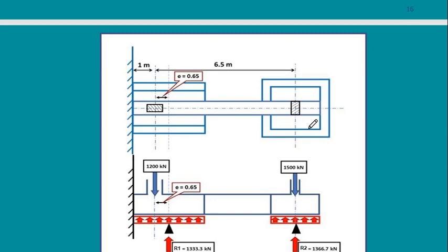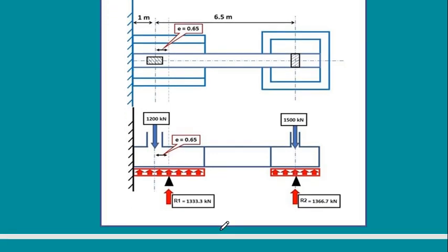What are the forces? Just for the designing of the footings, I was using the working loads because I'm just designing areas and so on. Now I'm going to design this strap beam. It's a beam. So I'm going to design the depth of the beam. I'm going to design the amount of steel. It means that I need the ultimate load in this case. But what are the forces acting on this beam?